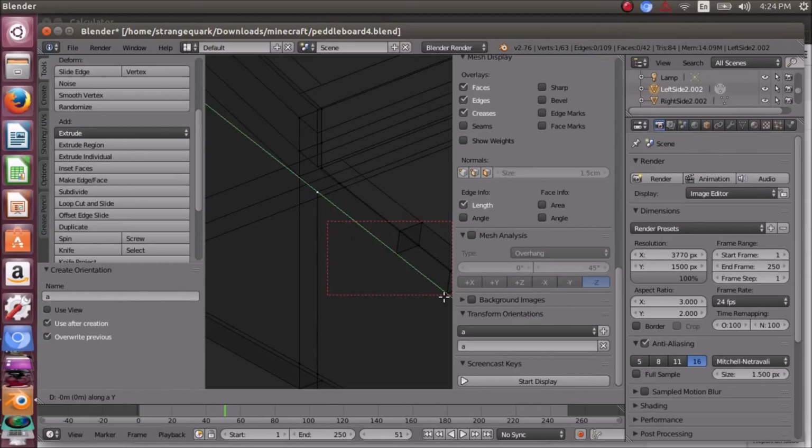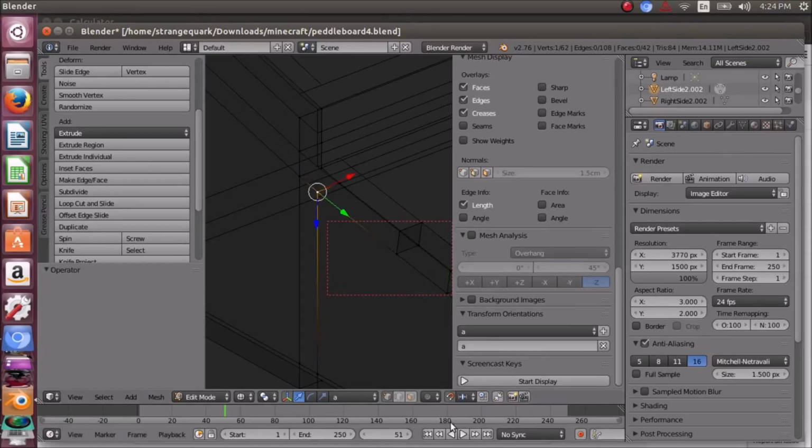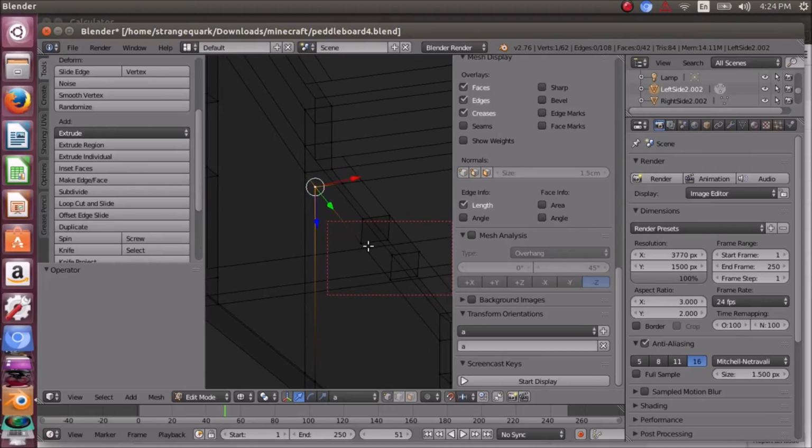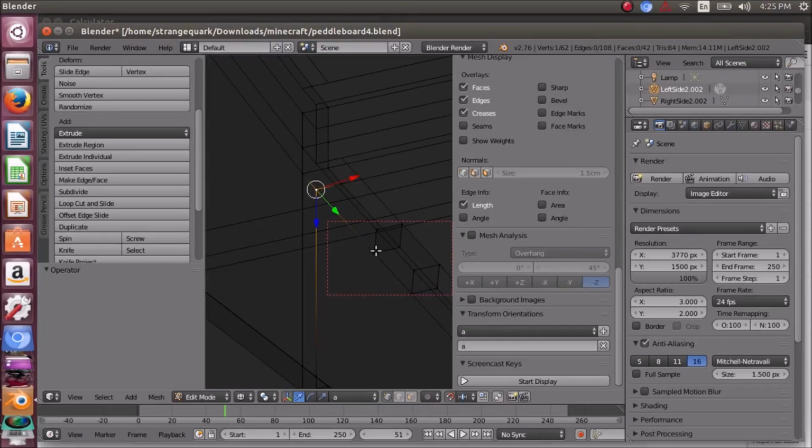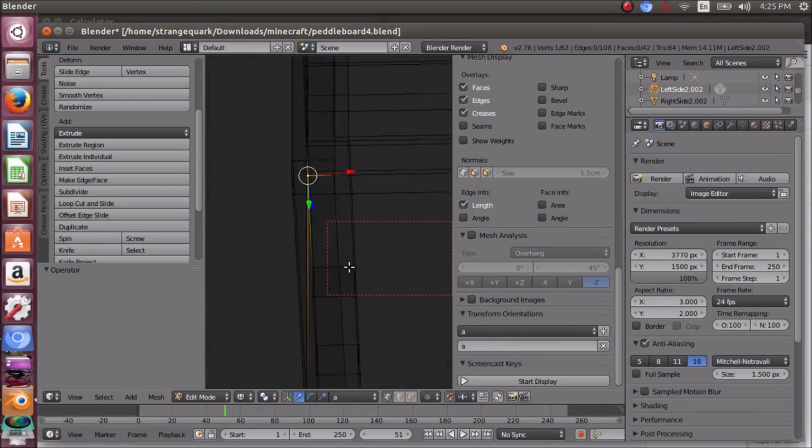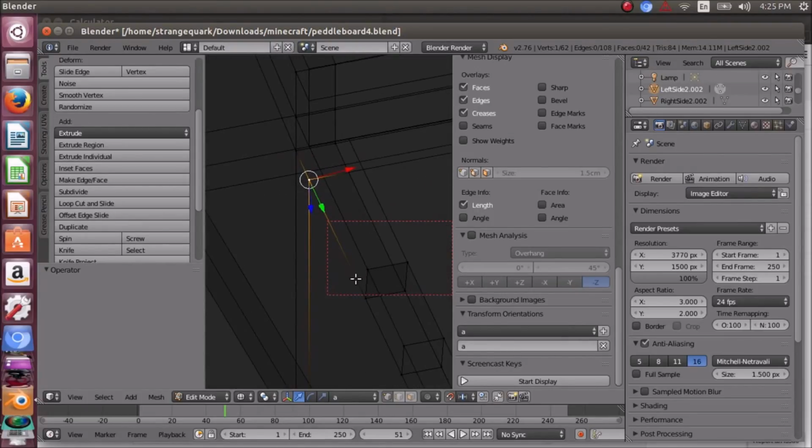I'll actually demonstrate it. Like if I didn't have this vertex here and I wanted to find it, and I already had it projected down here, so that I had an orthogonal line, 90 degrees, running between the two parallel lines, with a line or point projection from this edge and point to this edge and point, we could do so by just hitting E, Y, and then Y again.